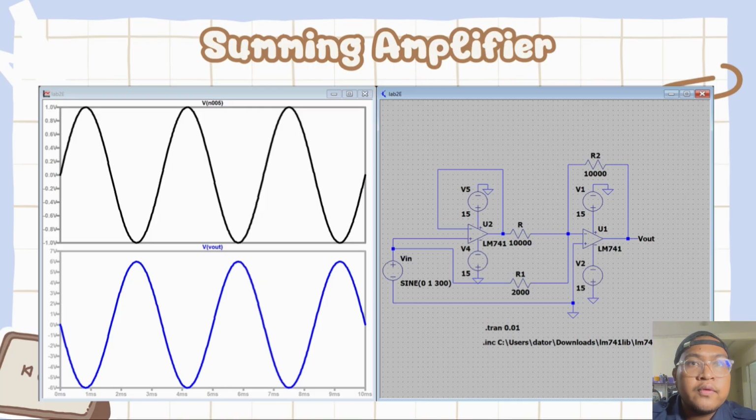The effect of this is the precise calculable gain formula. Conversely, the Schmitt trigger uses positive feedback, which is the cause of disabling the virtual short. The effect is that the op-amp locks to a supply rail, creating the hysteresis required for clean, noise-immune voltage comparison, a fundamental concept in analog to digital conversion circuits. This approach ensures our findings are technically justified, not merely observational.